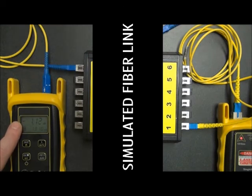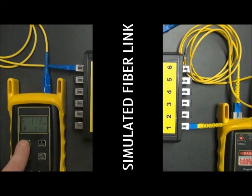We want to make sure that we actually see a negative sign here. If we do not see a negative sign, that means there might be some procedural issue that we'll have to address at a later time. So make sure that there's a minus sign here, and once we've taken our reading, all we have to do is simply press the save button here to save the reading at 1310 nanometers.